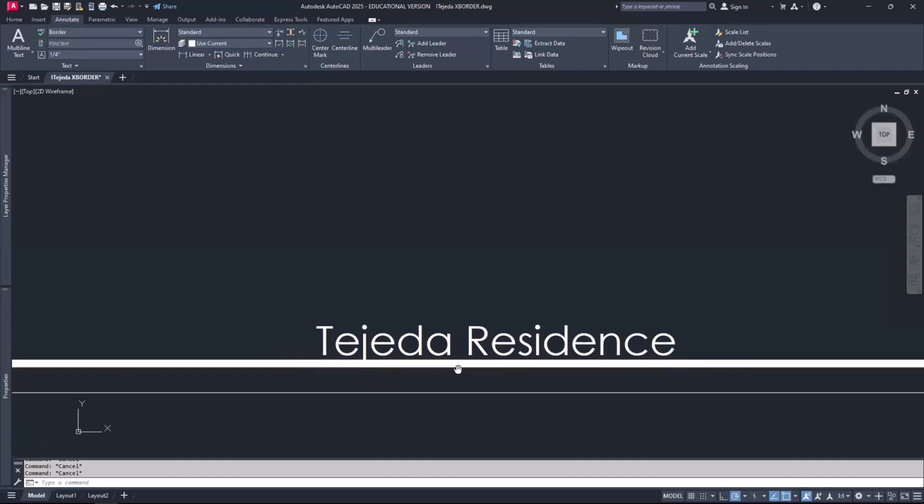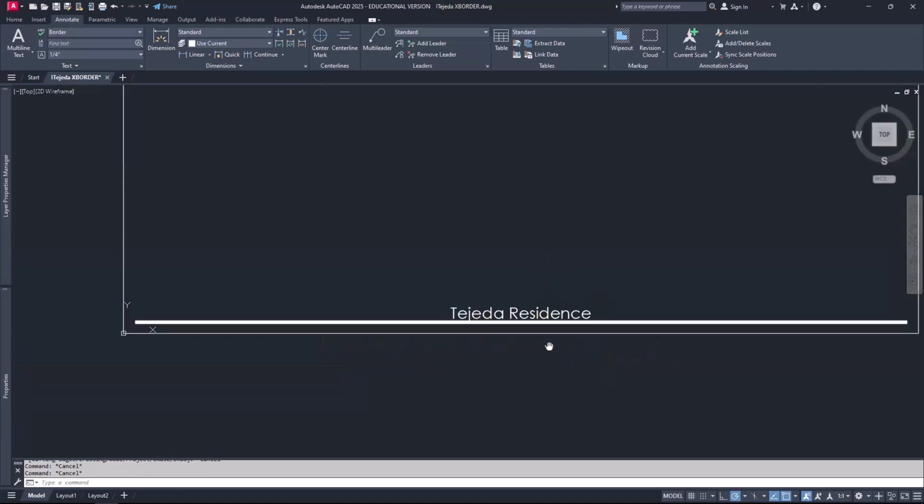And then there's something else I might be able to do, and that is to trim that line, the polyline right there. So let me try this. Sometimes it works. So I'll type TR, enter, and I'll select the polyline, select object. Are you going to let me trim? Let's see. No. Okay. It usually does.